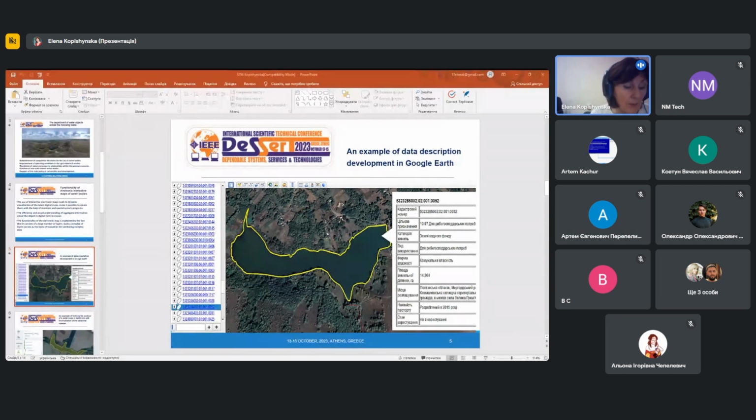To confirm the practical implementation of the proposed approach, experimental measurements of the bathymetry of one of the water bodies were carried out using the echo sounder. Such devices are considered the most successful tool for measuring depths, determining the relief of the bottom, and other underwater characteristics. For this, the Deeper Pro Plus Fishing Echo Sounder, which is equipped with a GPS sensor, was used. It can be controlled from a mobile device as schematically shown in this picture.